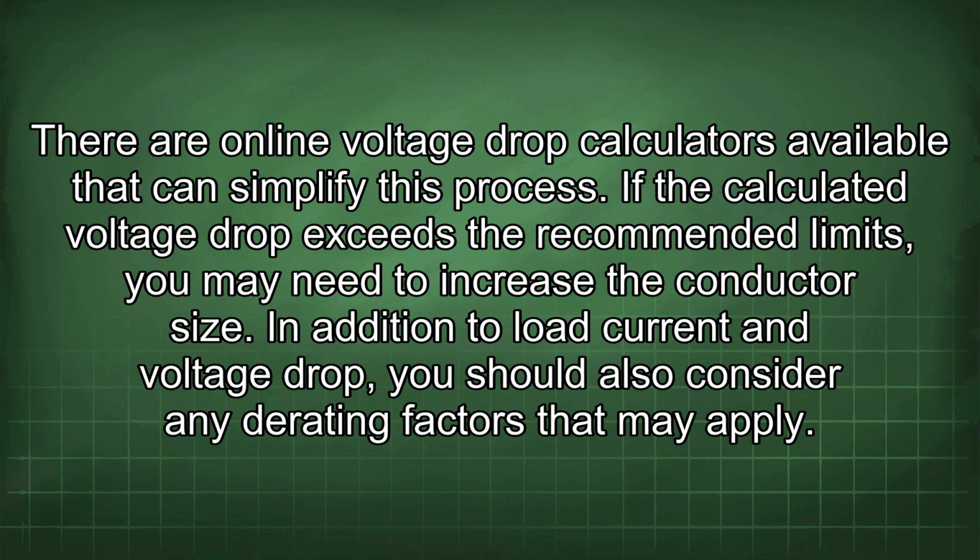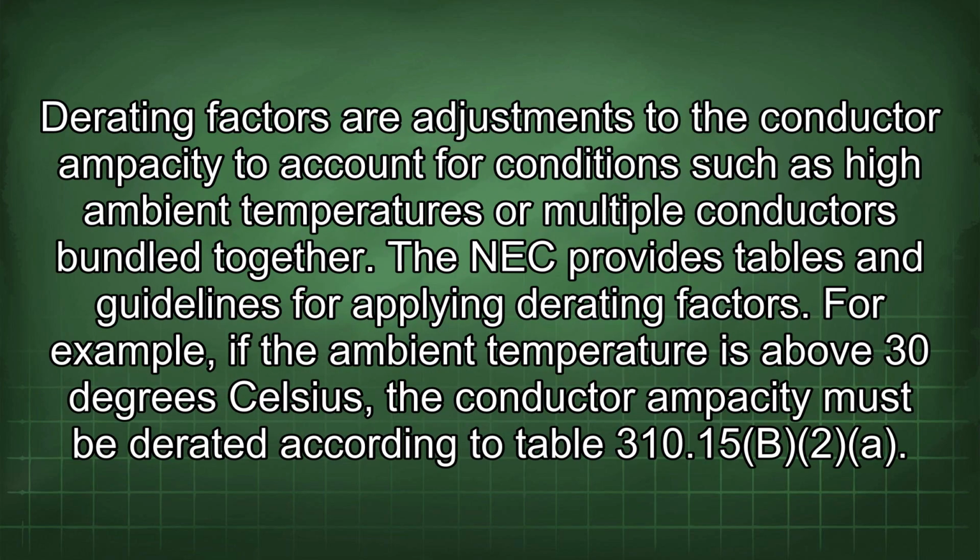In addition to load current and voltage drop, you should also consider any derating factors that may apply. Derating factors are adjustments to the conductor ampacity to account for conditions such as high ambient temperatures or multiple conductors bundled together. The NEC provides tables and guidelines for applying derating factors.